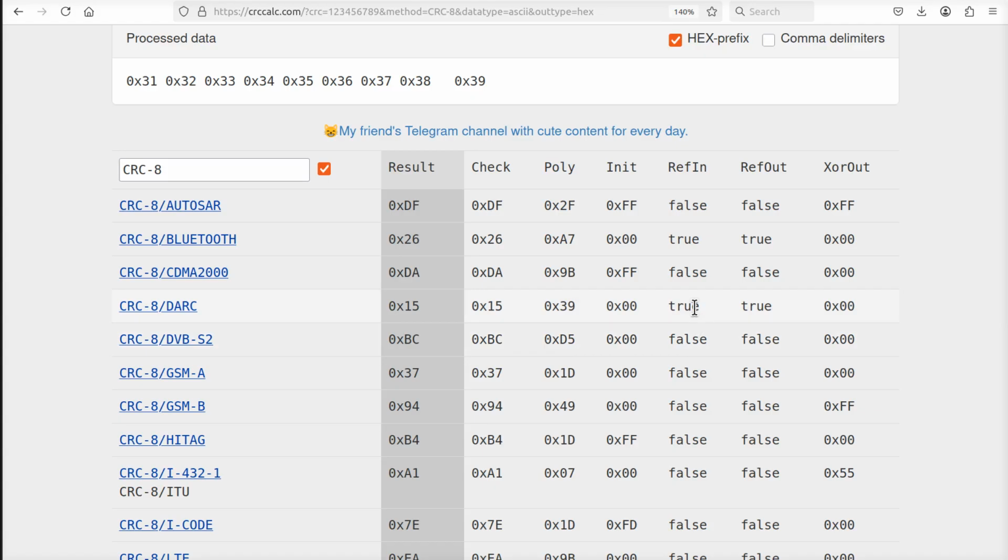Otherwise, you're going to have to load up an entire byte, or if you have a CRC16, read in 16 bits, then flip them all around, then clock it into your CRC generator, which is utterly stupid if you're going to implement a UART and the CRC generator inside your FPGA.